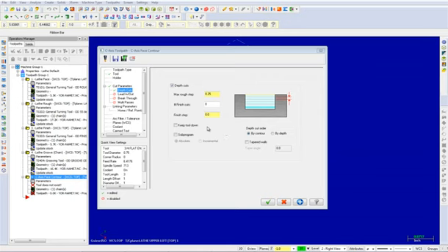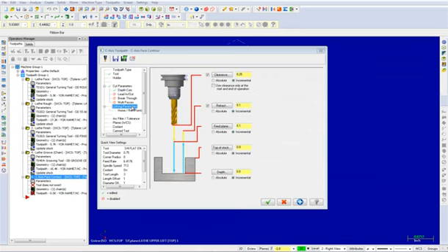Now select linking parameters. Enable clearance and set this value to 0.25. Also, enable retract and make sure the amount is set to 0.1. Ensure that feed plane is set to 0.1, top of stock is set to 0, and input a depth of -0.5. Ensure that all of the values are set to incremental.